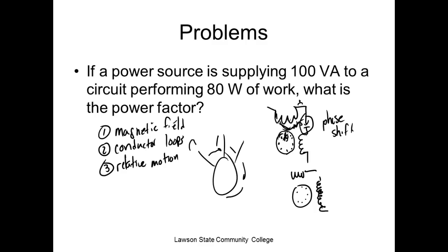Now, capacitive run motors, they have two capacitors on them. One of them is in all the time. If you have a true phase shift all the time, it can create more run torque. It won't create more start torque, but it creates more run torque. So they're more expensive, but the motors themselves are smaller. So if you're limited in the amount of space you can mount a motor in, then odds are you're going to use a capacitive run motor. If you're not, then odds are you're going to use a capacitive start motor. But the capacitive run motor is actually a capacitive start, capacitive run.